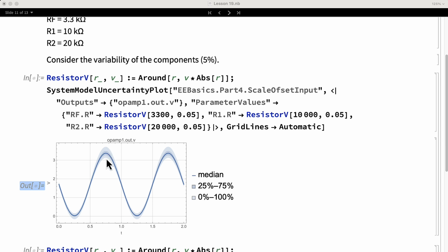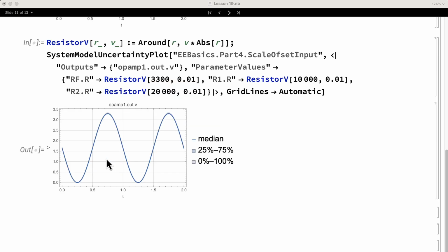as 3.1 volts. One way of reducing the problem would be to use resistors of 1%, which nowadays are very cheap. In the second plot, you can see the difference of using only 1% resistors. Another way of reducing the impact of the variability is to add a calibration step on the DSP side. For example, we can provide a constant 5 volts. On the DSP side, we can save the corresponding value in the memory. And we repeat the process for other voltages like 4 volts, 3 volts, and then we can use a table to get the actual values after calibration.